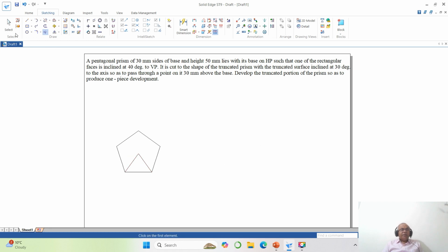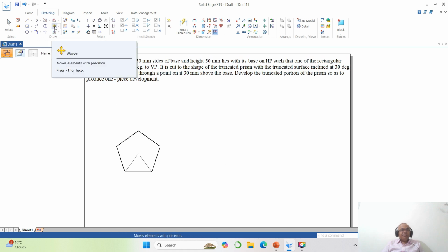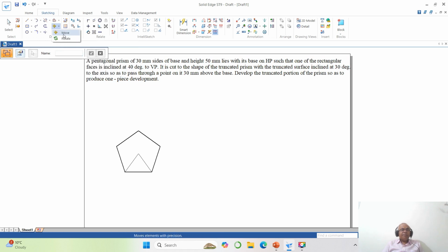Once you do that, now I will select all these 5 lines and make that as 0.5. Okay. Then you go to group, select this group, select these two and also these two and right click. Now you go to mirror, here.